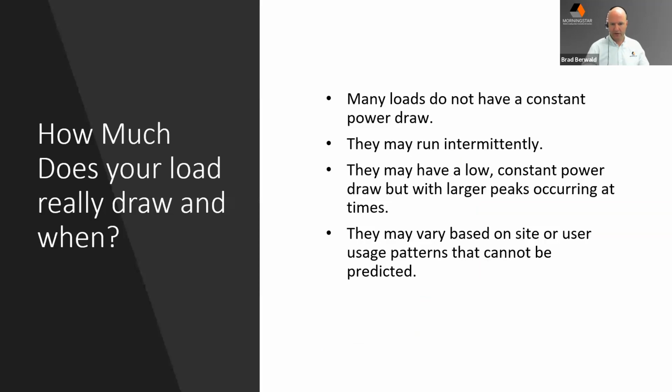Okay. So another question then, besides battery performance and of course what your array is generating, is what are your loads actually doing? Now, in a residential application, you're living with a system, so you have the ability to turn loads on and off, and you can get data from your inverter, and if it's a grid connected system, you can change the behavior of your home and your loads and how much power you choose to use. But in an off-grid system, the way you set it up to work remotely is pretty much going to run autonomously. So whatever that load is that's being powered, it's going to pretty much need to stay on all the time. And it may have some fluctuations in power that it draws, but you won't really be there to have an impact on it or control it.